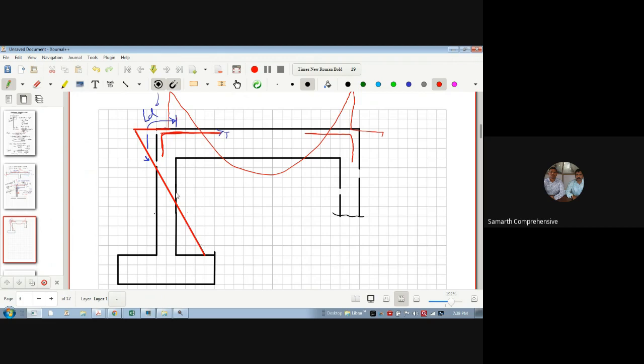As there is a tension, whenever you put any reinforcement in the column, let's say this is your reinforcement in the column. Okay. In this phase, this bar will be in tension due to this bending moment in the column. So it is similar to a beam. There is a tension in the column also in the reinforcement. So this tension which is there in the column, I need to transfer into the footing. So I need to develop this.